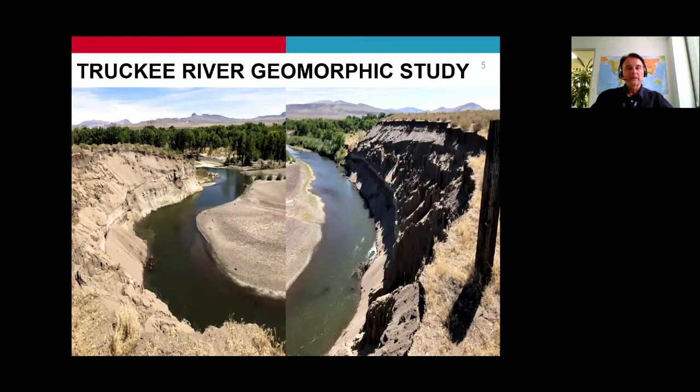The agency TURFMA recently initiated a fluvial geomorphic study for a 54-mile river reach to assess downstream impacts of flood control improvements on the river sediment transport capacity and erosion potential. This study serves as a screening effort to understand the potential geomorphic impacts on the downstream reaches with respect to changes in inundation extents, changes in flow velocity and riverbed shear stresses, potential for sedimentation impacts, bank erosion, and lateral channel migration, particularly at 7 critical areas of concern where significant bank cuts and meander migration was observed.